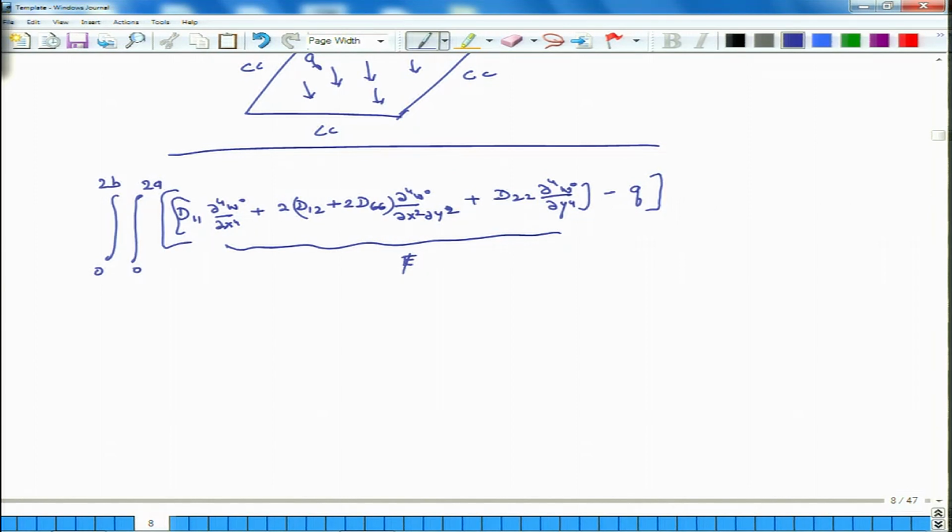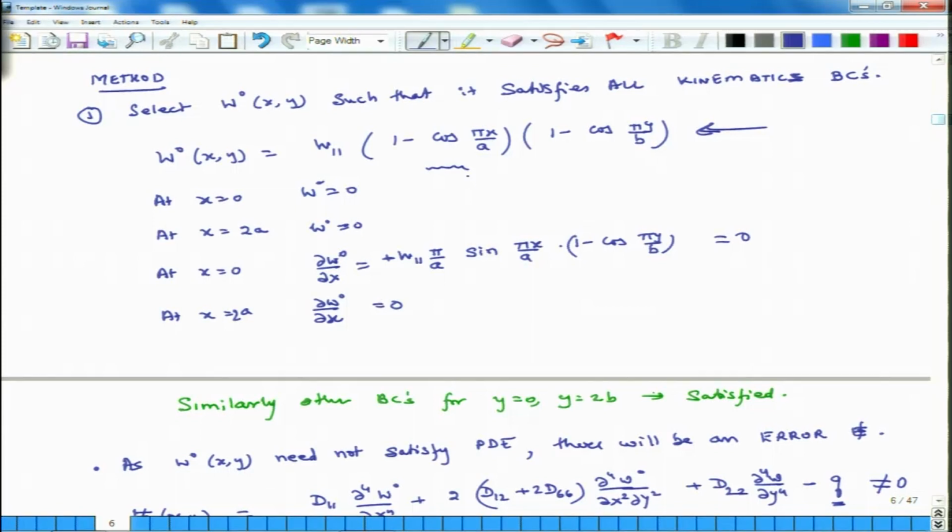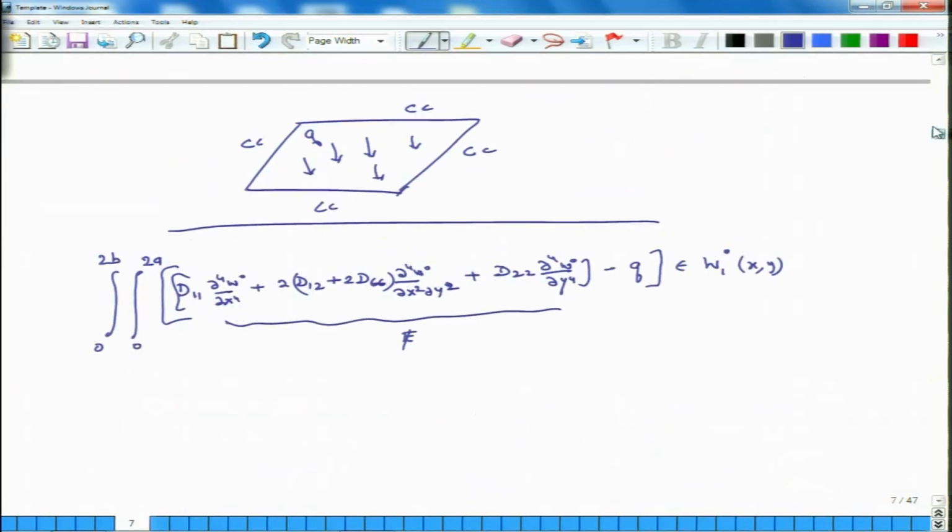and then I multiply it by virtual displacement, which is epsilon, and any function. So, this is the virtual displacement, and I can choose any function as long as it meets the kinematic boundary conditions. I can choose even the same function, a similar function which I chose earlier, does not matter, right. I can choose the same function, or I can choose a different function anyway. So, I have to choose some function w1, and then I integrate it over the domain, and I set this virtual work to be 0.